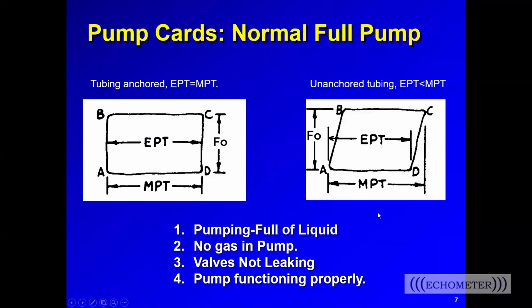So before we talk about incomplete pump fillage, let's talk briefly about what we expect to see when we have a full pump. These 2 illustrated pump cards, or synthetic pump cards, represent normal full pumps. You see the pump operation steps that I just went through from A to D. There's A to B, B to C, C to D, and then back to A here.